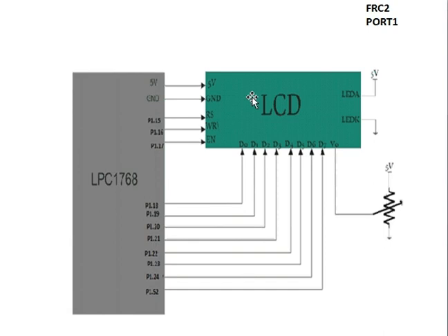Commands are signals which, when you send them to this LCD module, are used for applications wherein you may have to clear the screen, bring the cursor to the first line, or take the cursor back to the second line. For setting the cursor position, displaying, resetting, or clearing the screen, you can use different commands, and we will discuss 4 commands which we'll be using in this program.